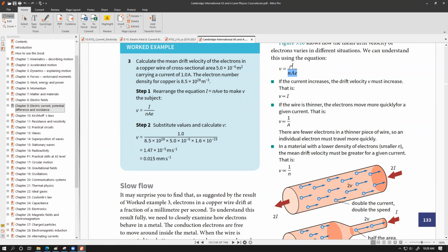We are dealing with the current. So you have to have a large enough voltage supply, and you have to have a variable resistor connected in series with that conductor. And obviously you're going to have an ammeter. What you're going to do is close the circuit and operate your variable resistor to make sure that the current is the value that you are doing all of your experiment with. If you want to keep your current constant, every single time you change your metal piece with a new one, you have to readjust the variable resistor value to get the exact same value of current.